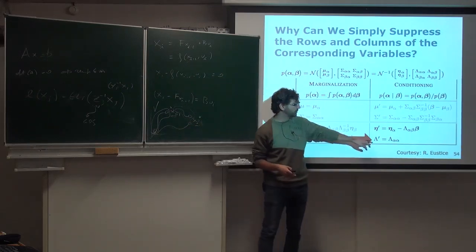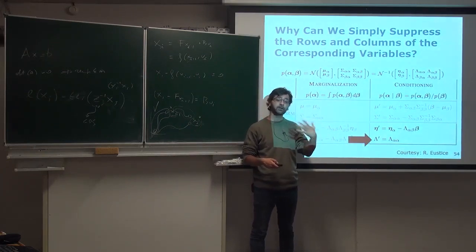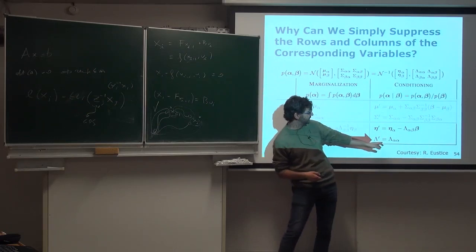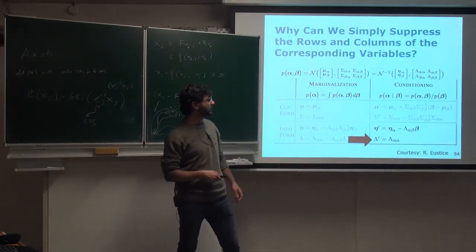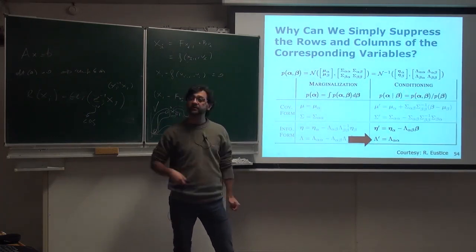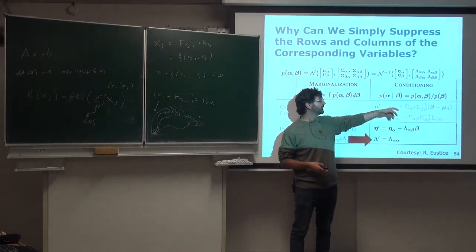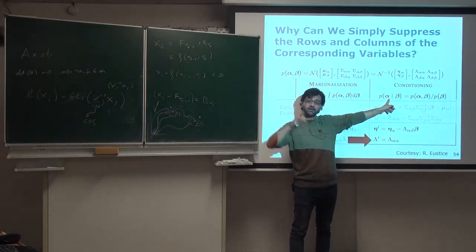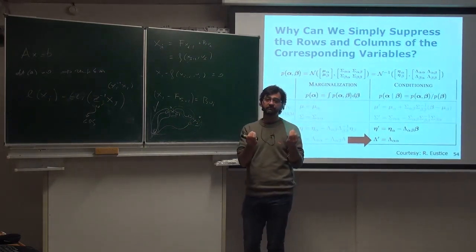By cutting out part of the information vector, which is the b's that we are now considering in the least squares formulation, and part of the information matrix, which is the Hessian that we have in our least squares formulation, what we are saying is that we are conditioning on a subset of the variables. So we are trying to find the maximum likelihood configuration of the remaining poses, given that we know some of them are fixed.